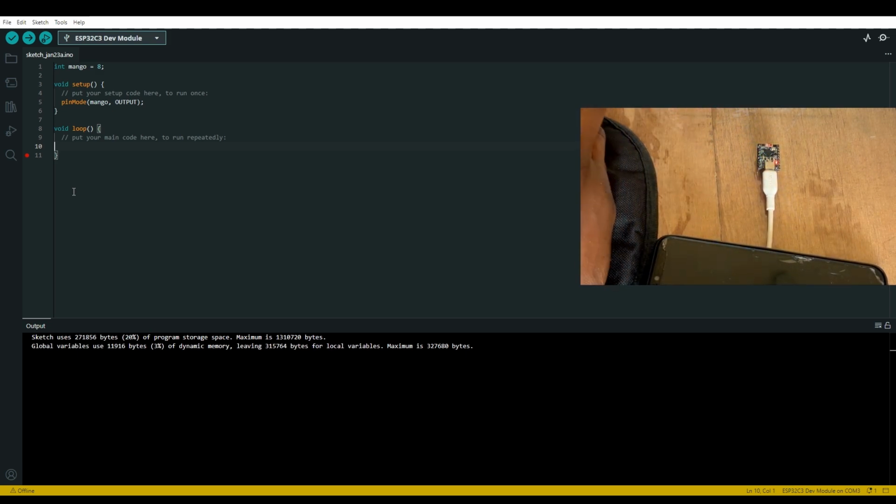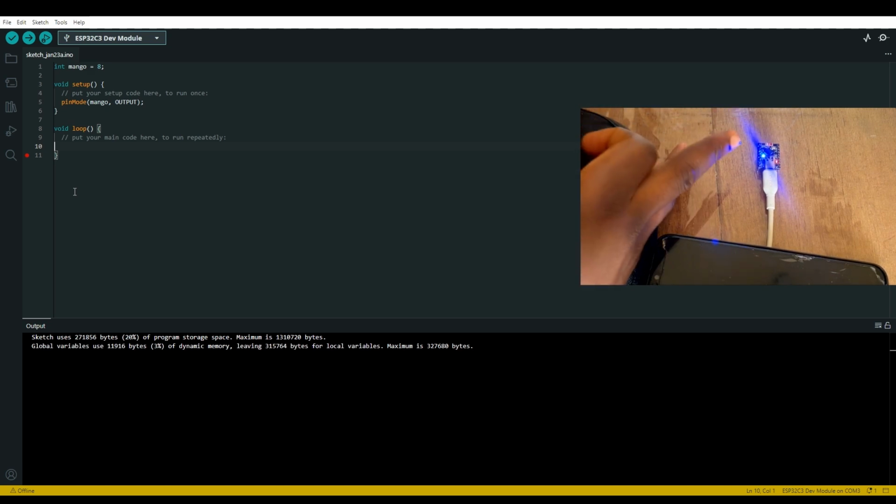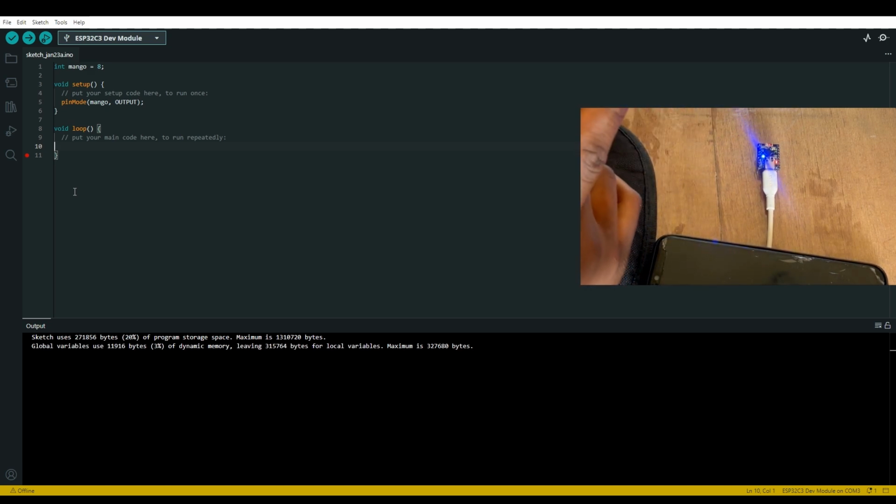So let's say if you pick 0, it is 0 volts. If you pick 255, it is 5 volts. If you pick around 100 or 150 thereabouts, you should have something around 3 volts or so. So the brightness of this LED cannot be the same if you pick a value that is low, far away from 255. The brightness cannot be as intense as it ought to be if you pick a value around 1, 10, 20 and thereabouts.